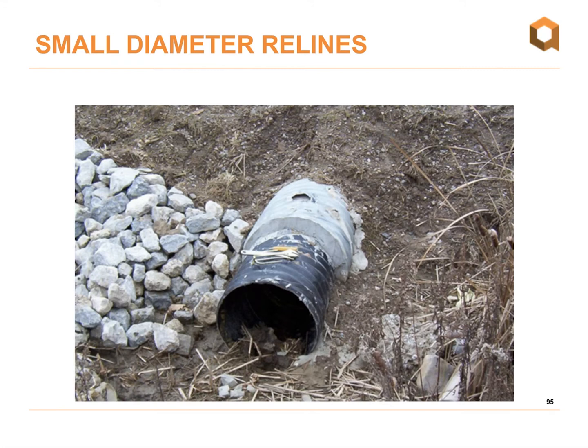And last but not least, to give you an idea of the total range of reline applications which are available from Armtec, we have here a small diameter pipe, which is being relined using a polymer laminate CSP pipe. You'll also notice, of course, we grout the annulus in these small structures as well.